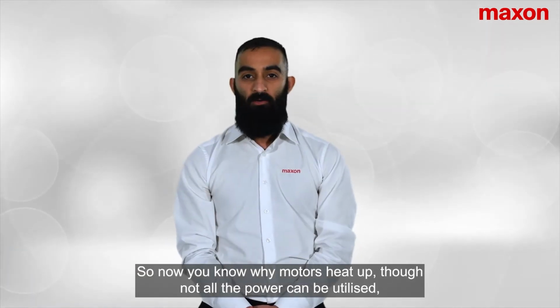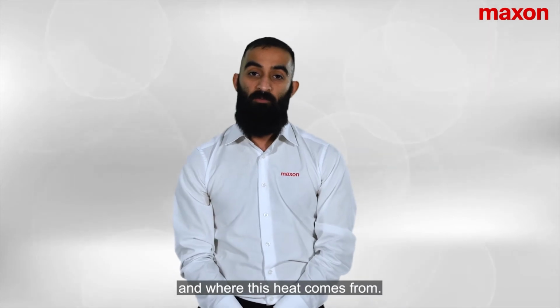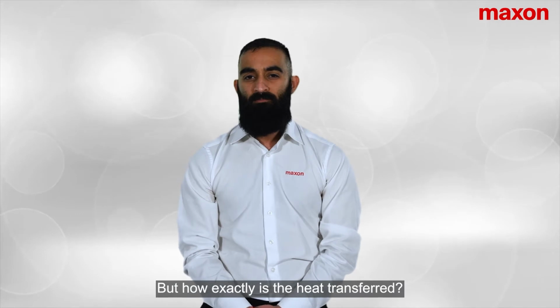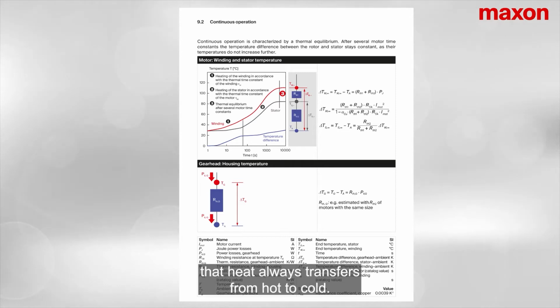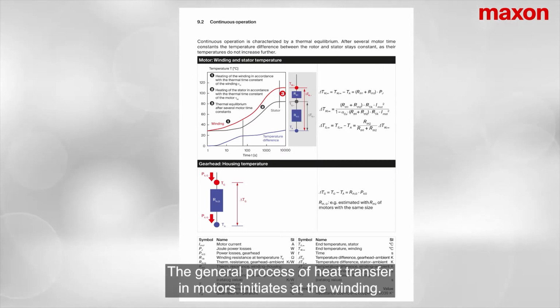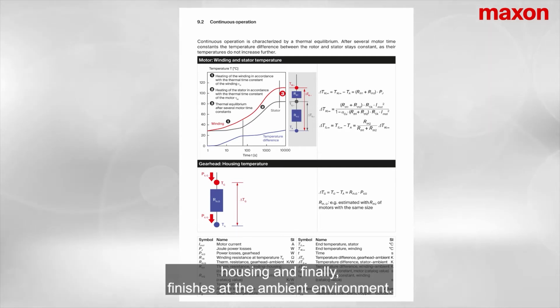So now you know why motors heat up: not all the power can be utilised, and the heat comes from the sources being the current and the electrical resistance. But how exactly is the heat transferred? Well, this is best described by thermodynamics, that heat always transfers from hot to cold. There must be a temperature difference. The general process of heat transfer in motors initiates at the winding. It then elevates to the stator housing and finally finishes at the ambient environment.